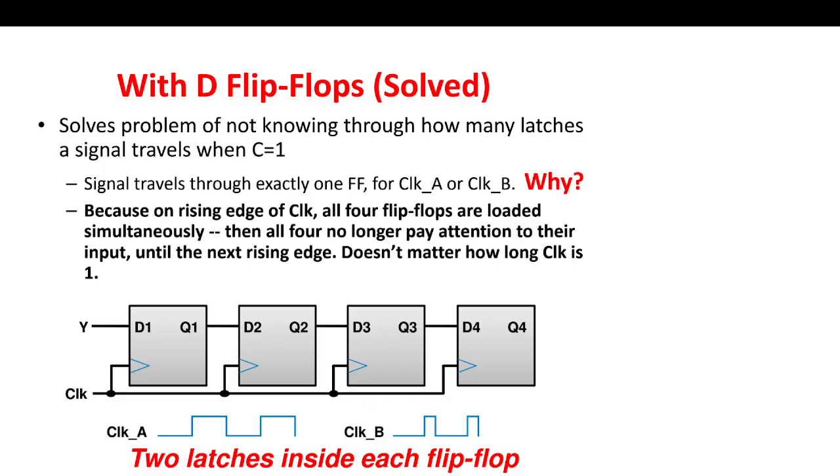Now, if we connect multiple such flip-flops, each consists of a master-slave combination, so now it is edge triggered. Whenever we represent D and Q like this, it is a latch, and whenever we put a triangle symbol, this indicates it is a flip-flop.